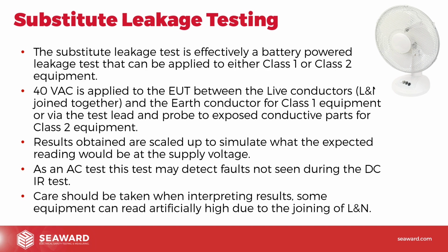So always be careful if you are carrying out these tests, because sometimes people just assume that the equipment's faulty or the PAT tester's faulty or whatever. And it's just the effect of the substitute leakage test, because we join line and neutral together. That's not obviously what you'd have under normal operation.